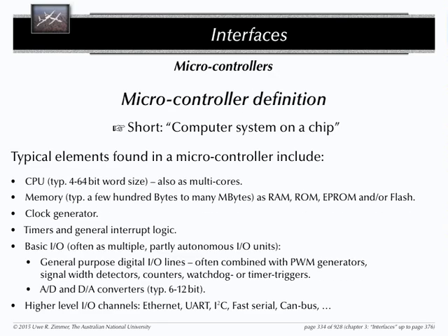A clock generator, so not the crystal, but the circuitry which is after the whole thing. Lots of interrupts, timers, lots of I/O, and these days you also have comparatively high-level I/O channels. But this is the bare basic. This is what pretty much every microcontroller has. In terms of CPU power, it's anything. You get 4-bit microcontrollers, you get very beefy 64-bit machines. As microcontrollers these days, there is no specific limit.